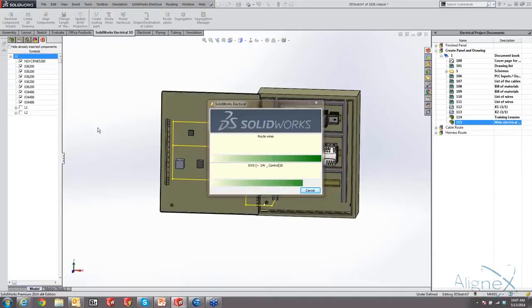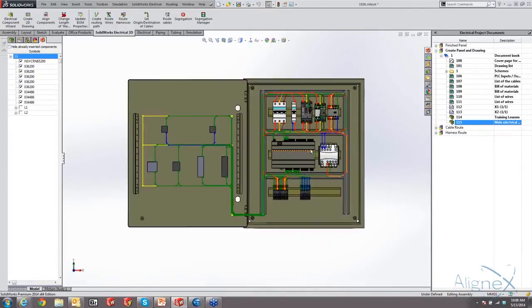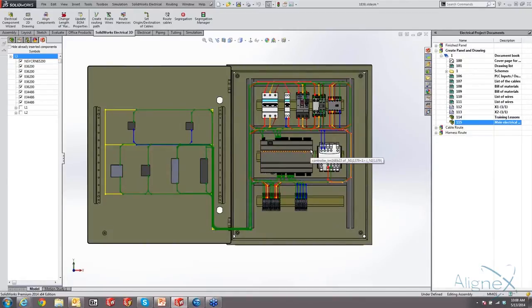Jeremy, while that's doing that, we have a question that's come in. The question is, how much is routing being used? Okay, you do not have to have routing in electrical to do this. A little bit later, we're going to talk about how you can use routing to help you, like route through clips and things like that. But what's happening is it's relying on the routing engine of SOLIDWORKS, but it is not part of routing. So you can have standard SOLIDWORKS and still be able to do this stuff if you have Electrical 3D. I think it's also worth noting that Electrical 3D does you no good if you don't have Electrical 2D schematic. The schematic tool is what helps you generate the schematics, and then we are going to rely on that in the 3D side of things.